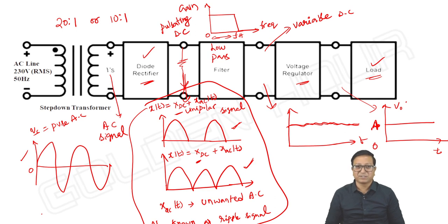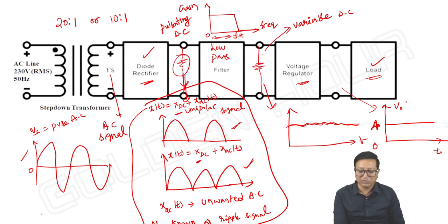What is its significance and what should its value be? We will check it. Next, along with the step down transformer and diode rectifier, instead of taking the load resistor here, I will connect a filter first, and then some load resistor, so that we see how the filter eliminates the unwanted ripples and gives almost a DC signal, a variable DC.